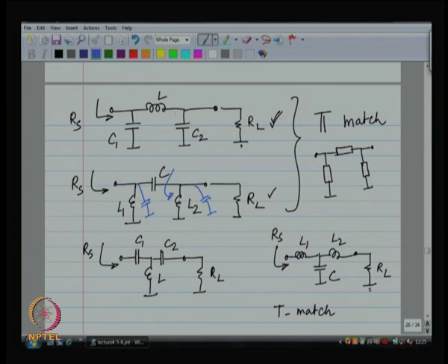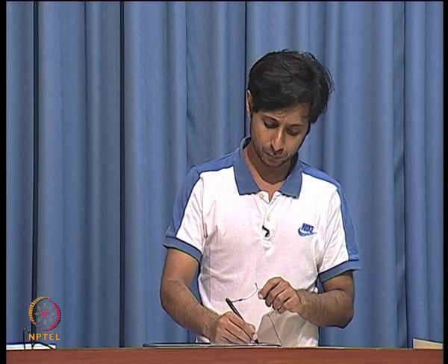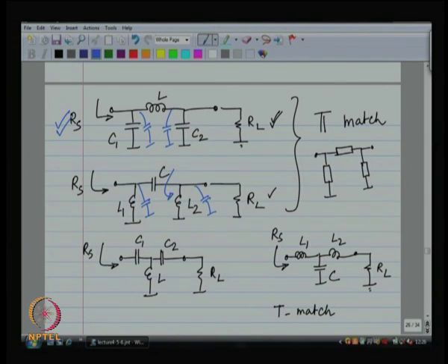Whereas, in this case if I have these parasitic capacitances, they can be lumped inside the capacitors. So, C1 and C2 can absorb these parasitic capacitances, and once I figure out what these parasitic capacitances are going to be, I basically design in such a fashion that C1 and C2 are so much less. The desired total capacitance minus the parasitic, I design it in that fashion, right. So, that is why I prefer this particular design as opposed to the next one.